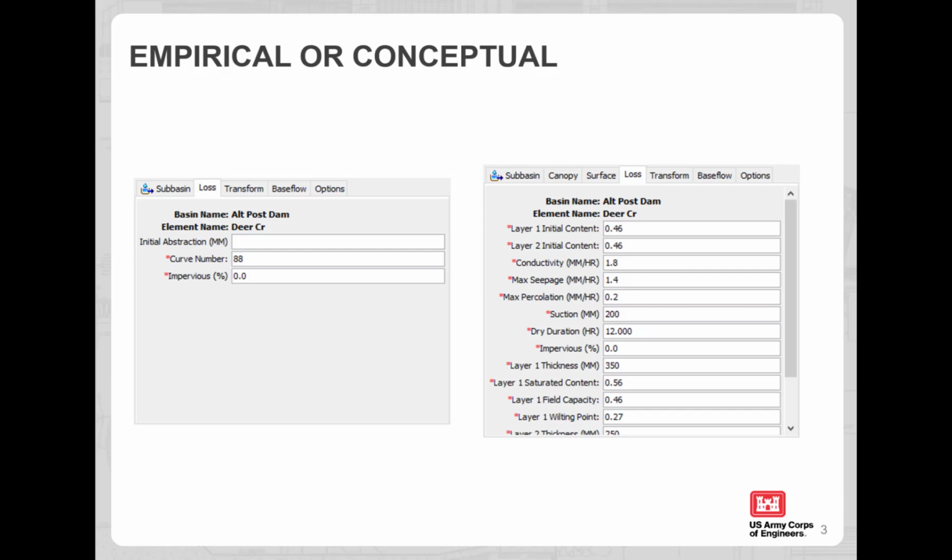One model limitation worth mentioning here is model coupling. Consider evapotranspiration and infiltration. In reality, you can't have one without the other. Because you are able to select different modeling methods for each element in the program, it is difficult to couple processes. The way we minimize errors is to use small time steps. Some methods use an adaptive time step to perform computations at time steps less than the selected computation time interval.